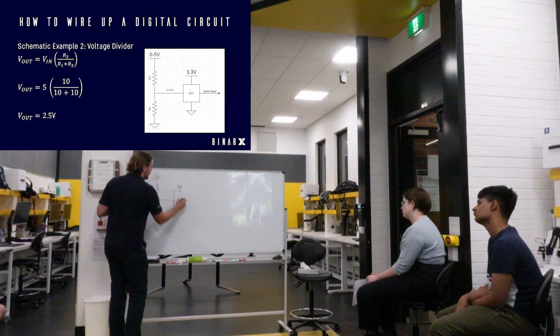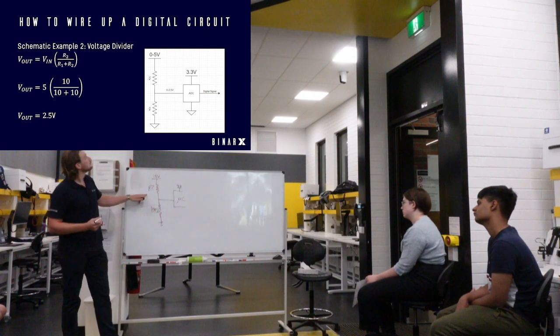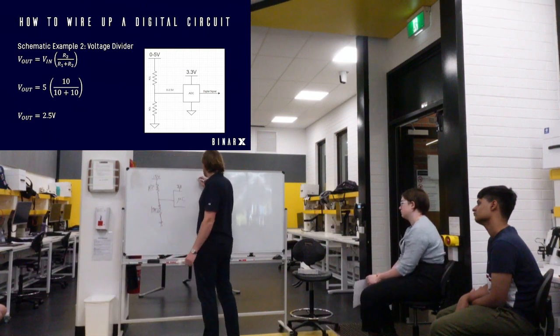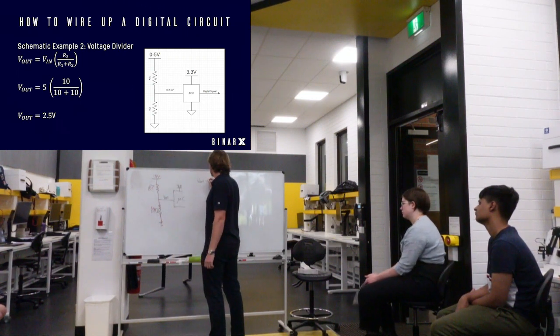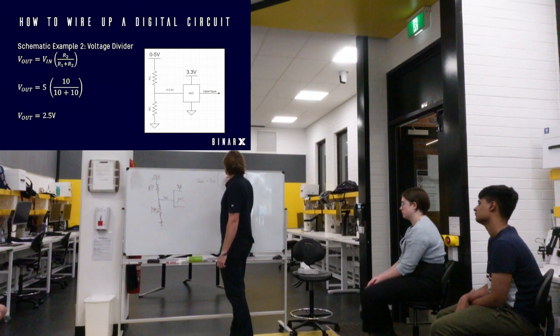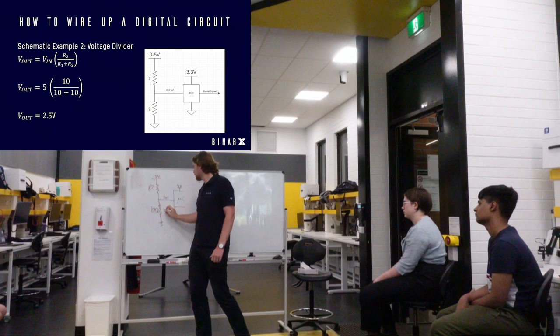So let's say this is our microcontroller, right? So if we want to calculate this resistance here, we have to use our equation. So we have our V out, which has to be a maximum of 3.3, equal to our V in times R2 over R1 plus R2. Right. I haven't done a very good job of showing this, but R2 is here. Have I got that right? I think I got that right.